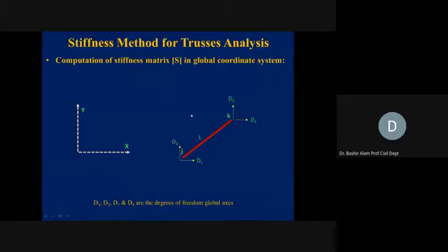Why? Because here at K it is hinged and it's a surface adjacent to this. So when you start pushing it to the right, shortening is going to happen in this element. Why? Take the example of when you drag it, let's say it is coming under this joint K. So this vertical distance is less than this diagonal one. Why is it less? Because shortening has occurred in this member 7. This vertical is less than this diagonal. So when we get shortening, it is always because of the compressive forces.